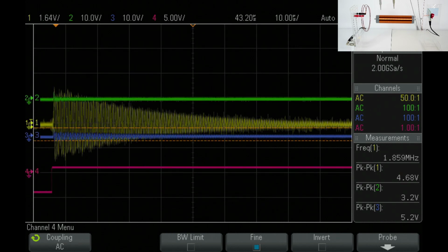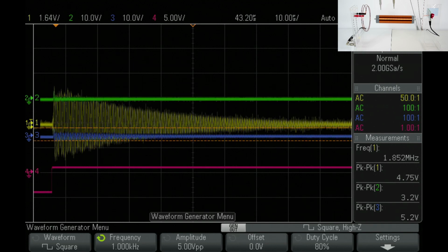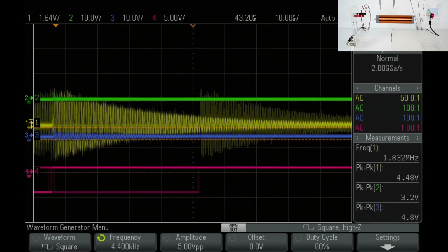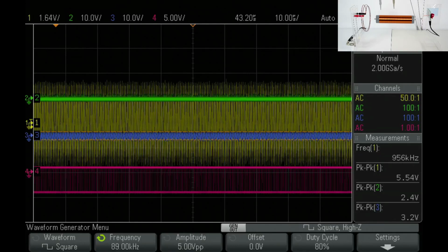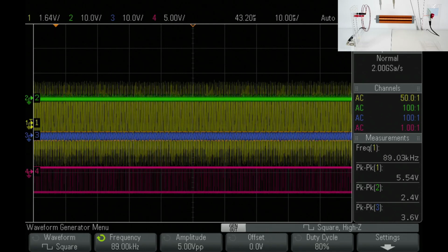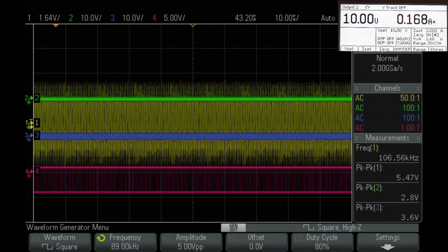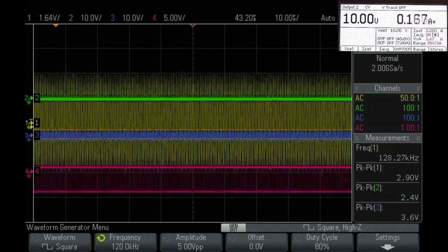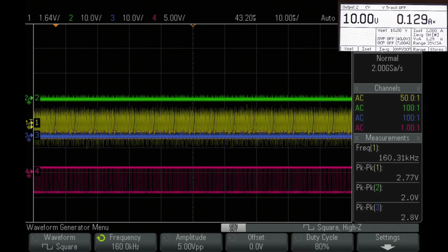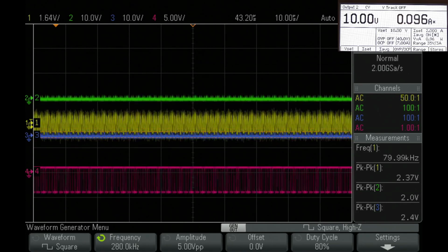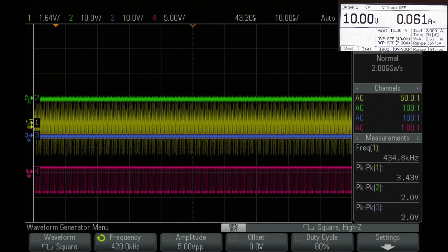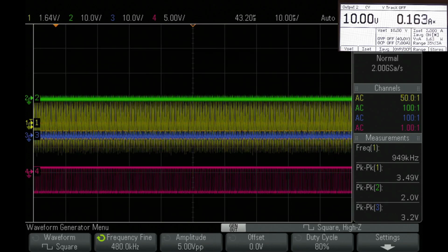So we start with the frequency of the so-called first lower harmonic. The frequency would be around 468 kilohertz. Sorry, I need to change the view here. You have to look at the power supply: 1.6 watt. If you go to 468, that's something I would like to bring your attention to, the power requirement at the various harmonics. So 468. This is a quarter.